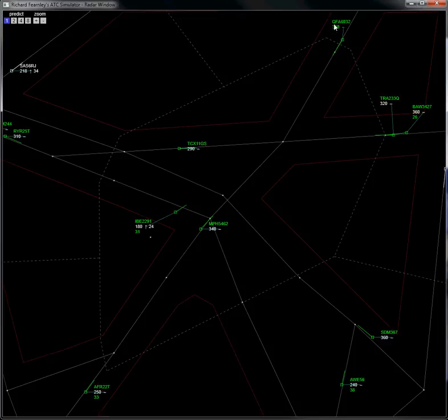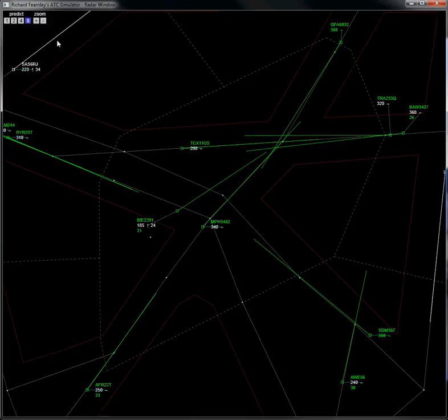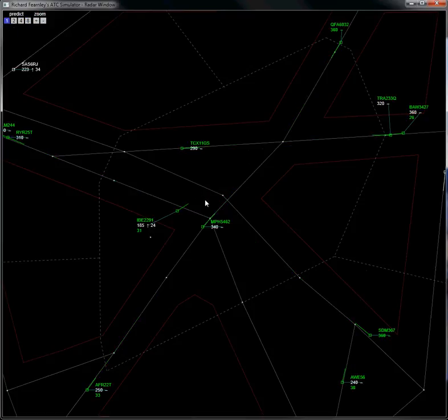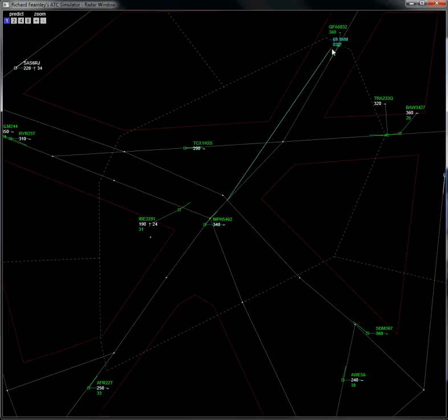I can see here I have the Qantas 6032, flight level 360, and down here I have a Russia 367, also at flight level 360. If I switch on my 8-minute probes, doesn't really tell us much, so if I were to take the QDM tool by left-clicking to analyse the distance of the aircraft, we have here 72 nautical miles, and we have here also around 72 nautical miles, so these are in conflict.